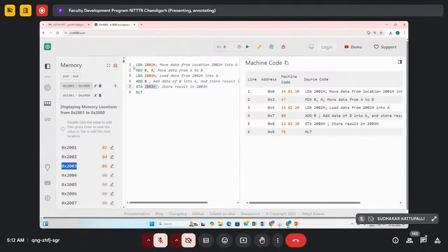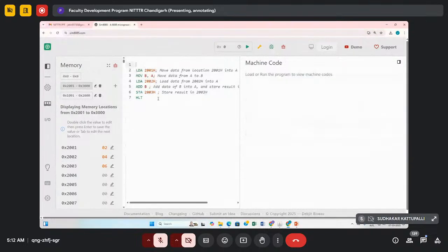Okay. So we need to have a register in which we'll be storing a carry. So let us initialize C. We'll be storing the carry in register C. So why have I moved 00 in C? Yeah, we are clearing it because here we know it, but when we are specifically working on the microcontroller, we might not know what data is there in C.